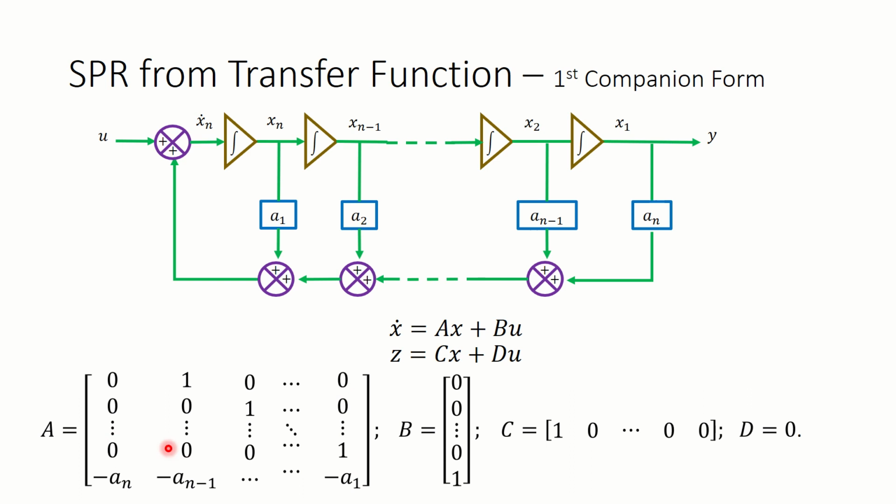This is the form of the chain of integrators, because when you draw the block diagram from this, it looks like a chain of integrators. Now this integrator chain will end somewhere. It ends with xn dot. We can't have any other integrator here. So what is xn dot? xn dot is all this expression that comes here.